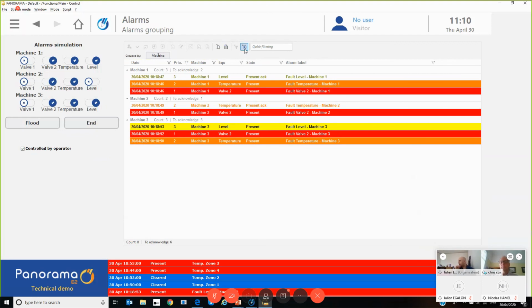So as Chris mentioned, because we got the question, filtering alarms out can be dangerous. Is it made clear and obvious that a filter is currently applied or not? Could a user-defined indication be added to alert the user a filter is currently active? So we recommend what you see on your screen. There is a bottom banner which deals with the current alarms, which has to be always displayed on your screen, whatever you do, and a second part to select, to filter, to manage, to handle, to analyze your alarms, switching between different modes. That is the right behavior we recommend.